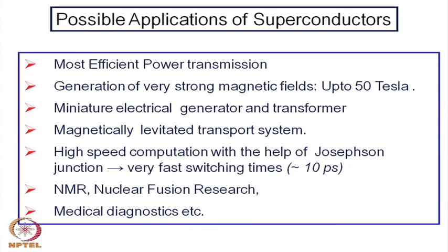Of course, the ideal is if one can get superconductors at room temperature, so there is no question of any refrigerant needed to operate the system. There is still a lot of advantage if one can make use of liquid nitrogen at least as a refrigerant. So, cables have already been designed, and experimental cables are in use for transmission of very large power from one point to the other. Of course, there is an inbuilt refrigeration system.